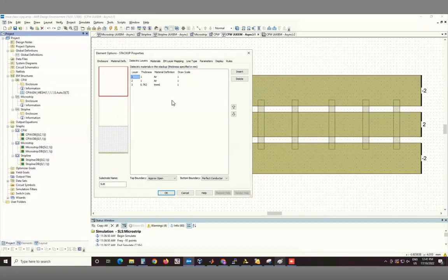Ideally, as short as possible. That will have some path. It has basically this kind of size scale. We will say that that's an inductive connection, right? The lower the inductance of that connection, the less the potential difference you can have across it. So what you really want is a true short circuit, which of course doesn't exist. So you want to make it as close as possible. Having a solid line like the one we did before does create that effect.